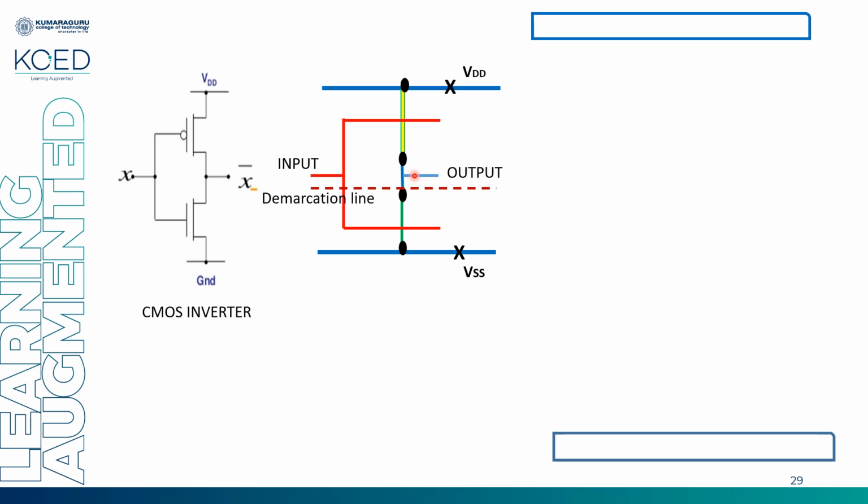Once the stick diagram is done, go for the representation of layout. If you know the CMOS circuit, the transistor based circuit, you can easily draw the stick diagram. And once you are done with the stick diagram, you can view it and parallelly represent your layout very easily. Similar to the stick diagram, first I have drawn the VDD and ground. Again, hope you remember. In case of stick diagram, I can place polysilicon in vertical or horizontal mode.